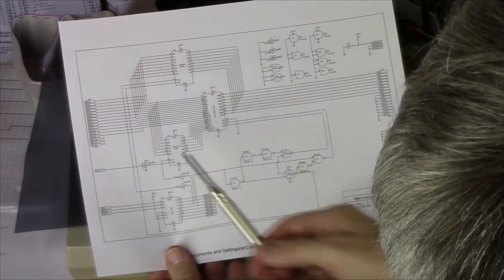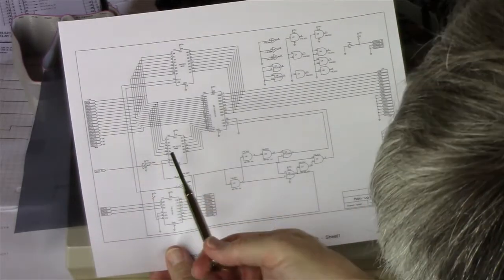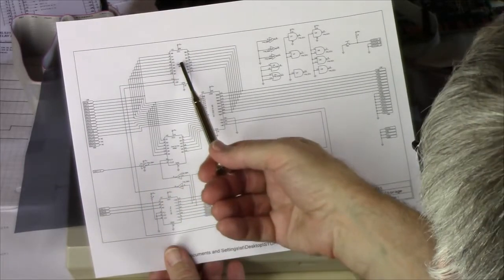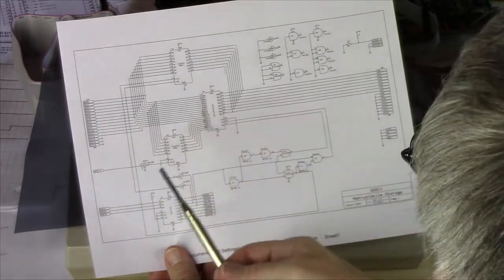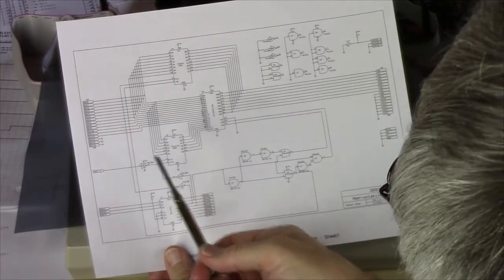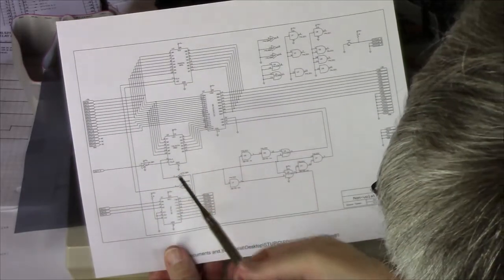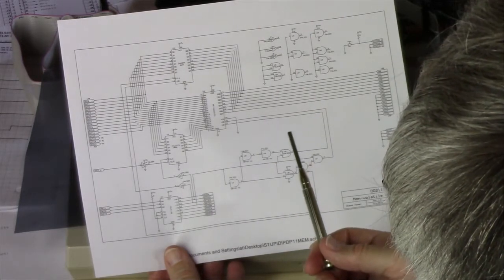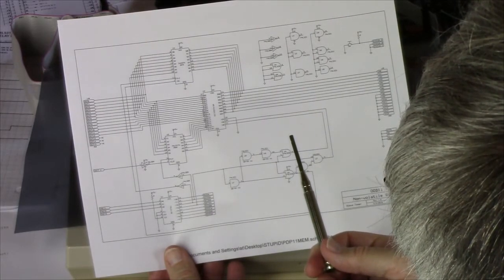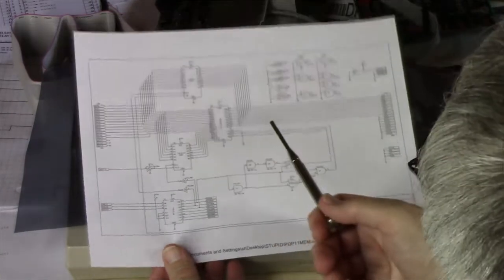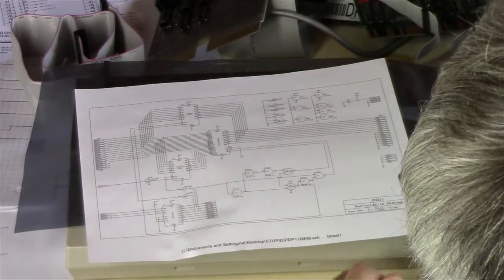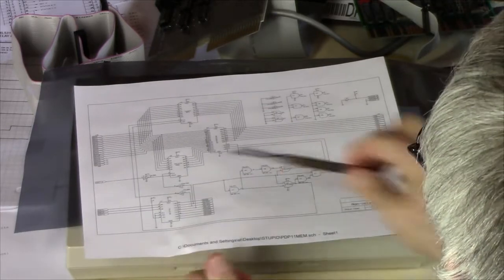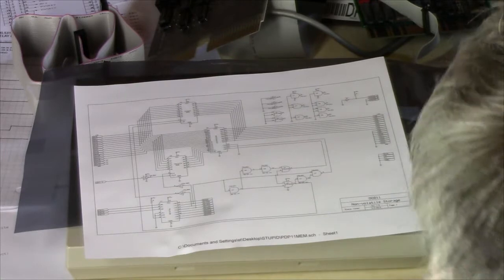because for a write, we've got to first, well, of course, we'll set the page register somewhere in here, but for a write, we've got to set the data into the data register. Then, okay, set the page register, put the address on here, and then we say write. Then, of course, because of the way these chips are, we have to wait for that write to complete, but that's just doing a bunch of reads. So the write is, as you see, more operations